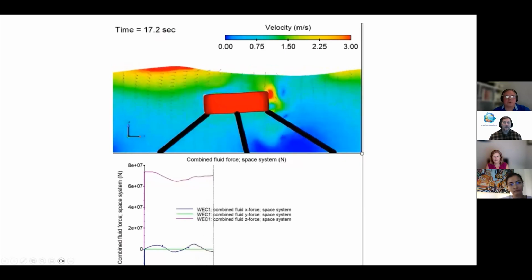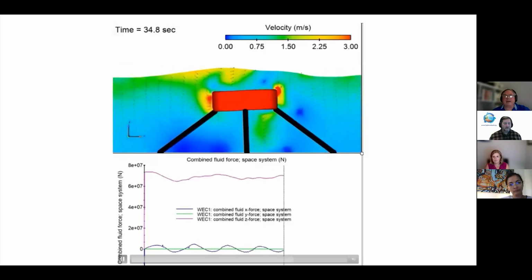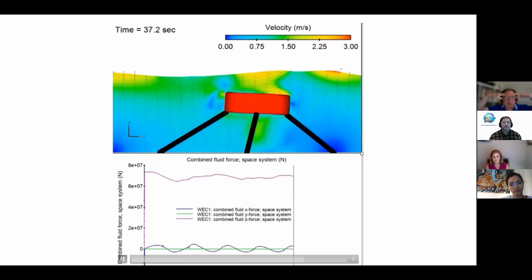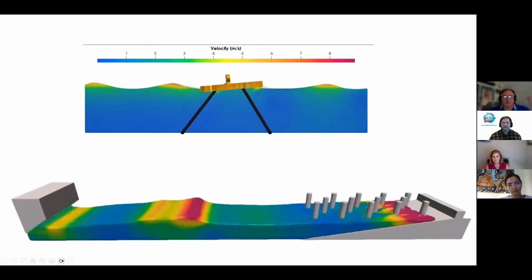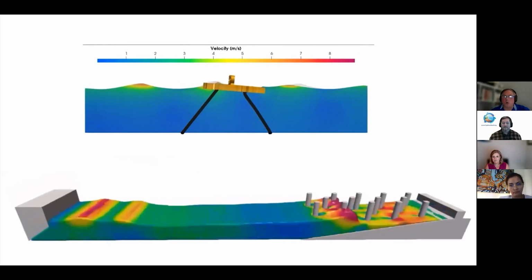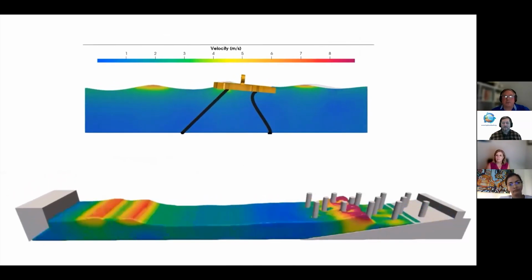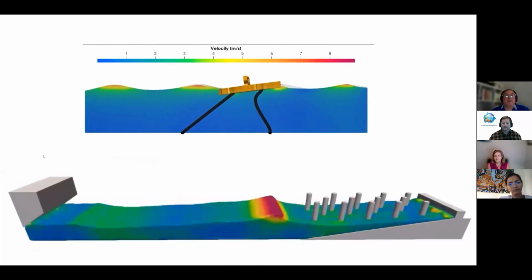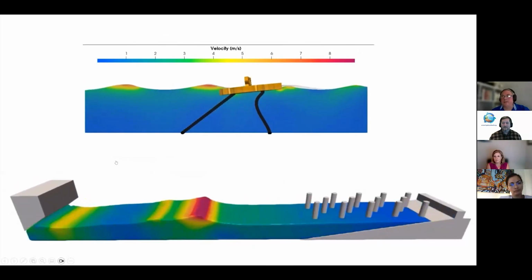So for oil and gas, Kim is 100% correct. You cannot simply take an offshore oil and gas platform and plunk an offshore wind turbine on it. The oil and gas platform is designed essentially for a dead load, the weight of the equipment on the platform. So you're looking at your soil resistance in the vertical direction. An offshore wind turbine, it's doing this. So you're looking at your soil resistance in the horizontal direction. Totally different. And it's actually an area where we've had to do additional research because we simply didn't know enough about horizontal lateral loads going through soil. So it simply can't do that.